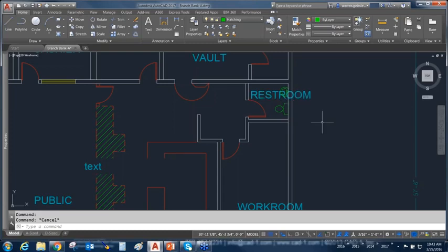I've not tested that out, to be quite honest, to see how those grips can react on an annotative block inside of a dynamic block. So the best thing that I could recommend is that it's very similar to what we were looking at for text. What I would assume is that all of the grips are going to be separate on a scale-by-scale factor. So that would be one of those where, depending on what it is you want to do, you're going to want to test that out and see how it reacts on each one of the scale factors.